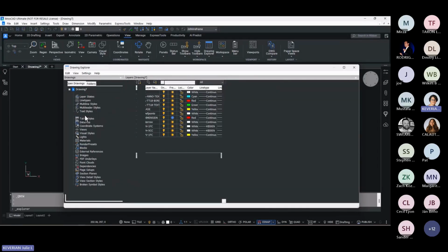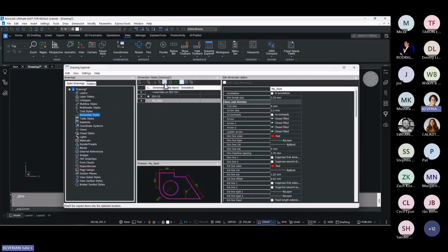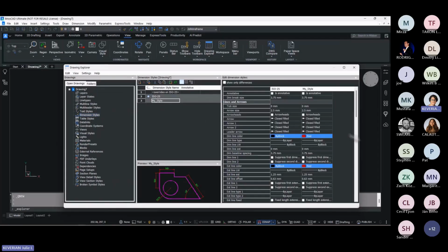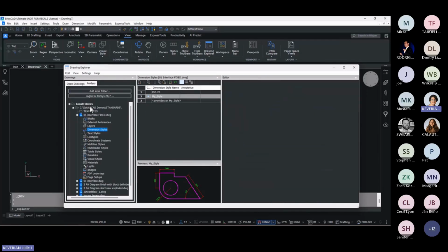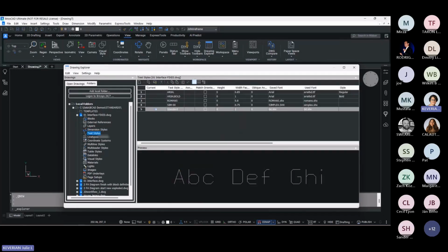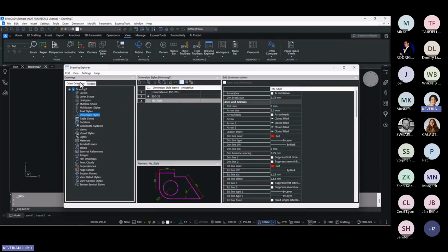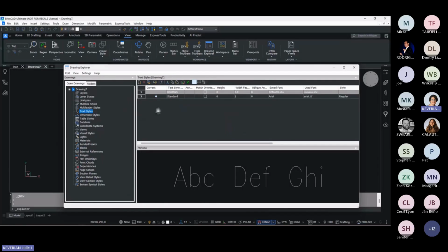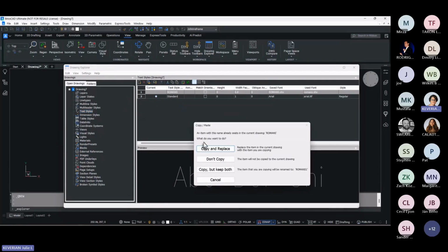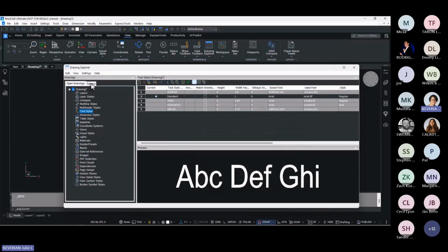to reuse. Now remember, the Drawing Explorer folders feature lets you mine data from unopened drawings, again, making it perfect for building your templates. I don't recommend putting a lot of blocks in your template files unless you are certain that those blocks will be used. Blocks are better left in their block libraries to be utilized as needed. That way you're not cluttering up your template file with unneeded content.